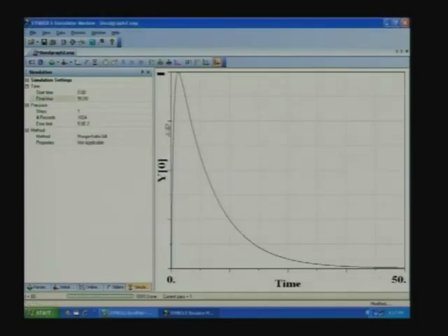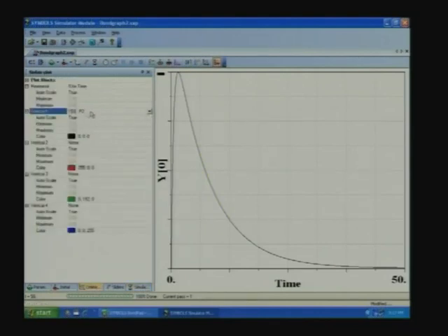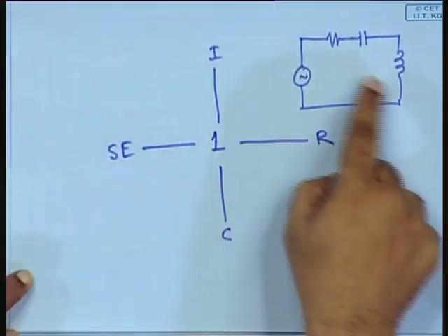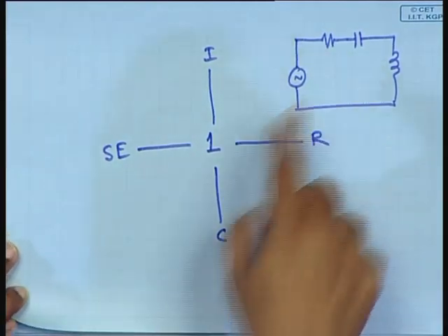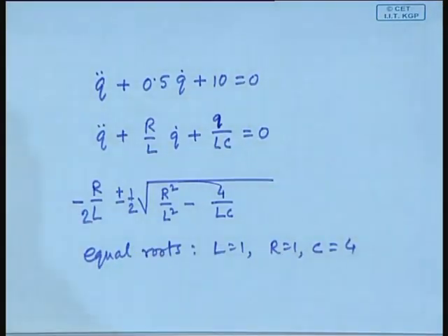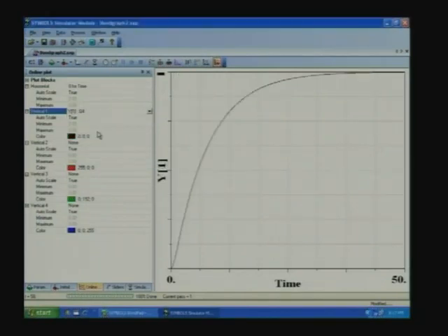Okay. So, it goes and then, now what did I plot this time? I plotted time and P2. P2 is the current through the inductor. Notice the circuit, the current through the inductor, because of the capacitor, must go to 0. So, it goes up and goes to 0, but what is the capacitor voltage? That will stabilize to some other value. So, if I plot something else, say Q4, it is stabilized there, fine, but this is an overdamped system.